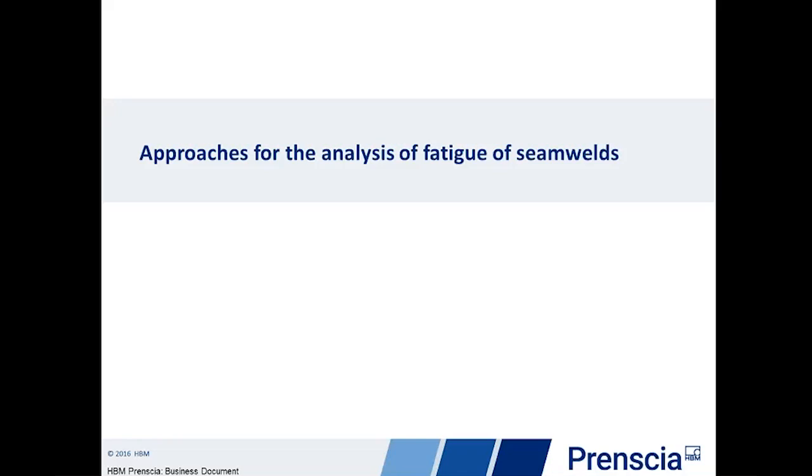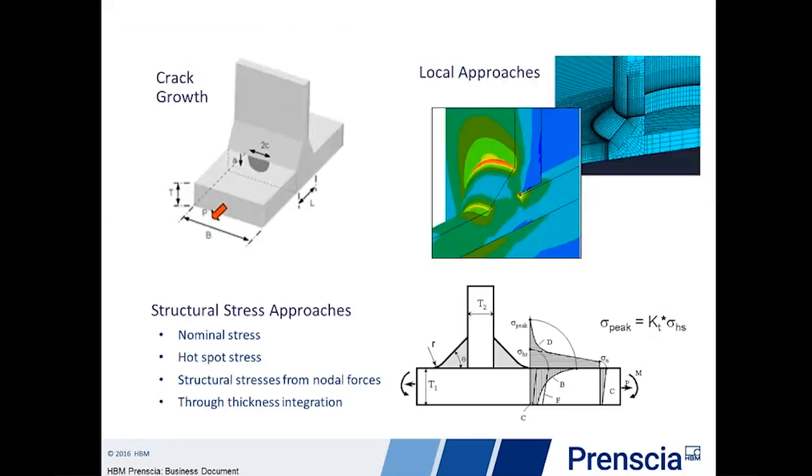With that said, we have to look for approaches to go off and analyze welds for fatigue. And there are several that we can look at, one being crack growth. I had mentioned that welds behave primarily in crack growth. The issue with crack growth is, one, it's a very point-wise solution, and it's very sensitive to the starting points. So basically, the initial crack size, crack shape, direction, all have a huge impact on the final answer.